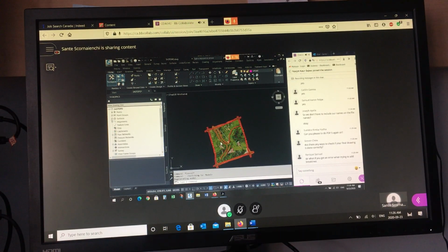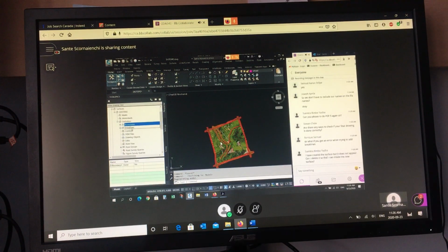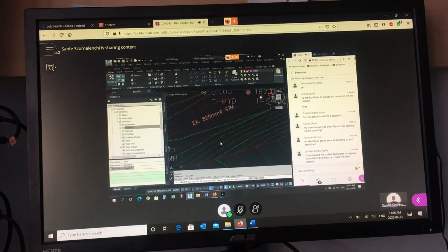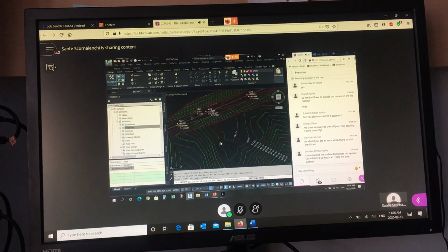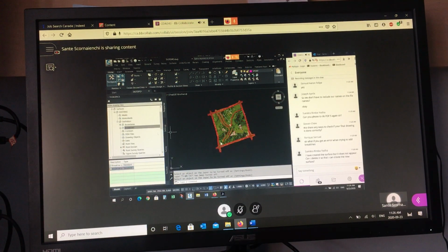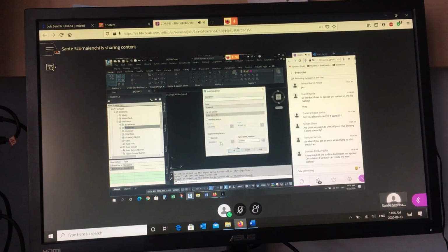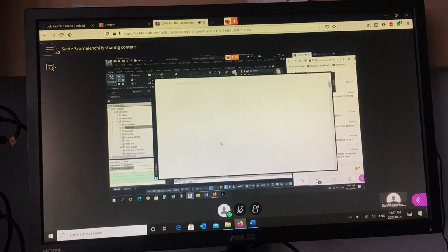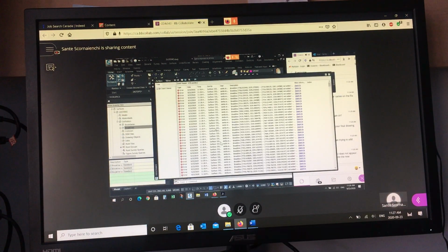I think I can duplicate that. If I go to my surfaces and I delete the boundary, if I delete these break lines, or I can define them again maybe. Let me just do that. I'm just going to turn off the surfaces. So all the break lines, all the polylines are there, and I'm going to add them. And then I'm going to use proximity. So when you do this, you get a whole bunch of errors. Just ignore them.